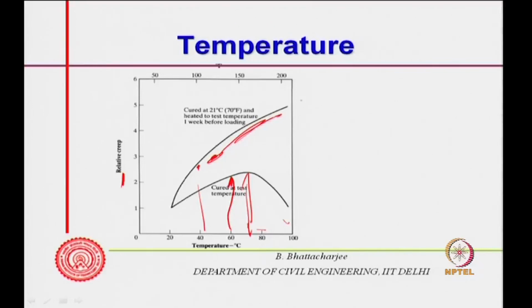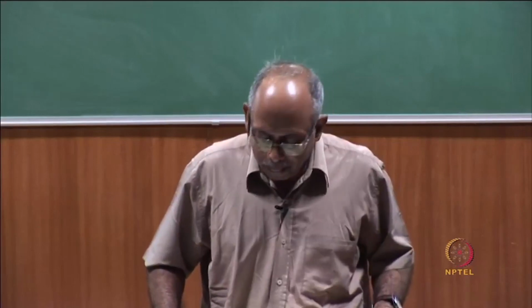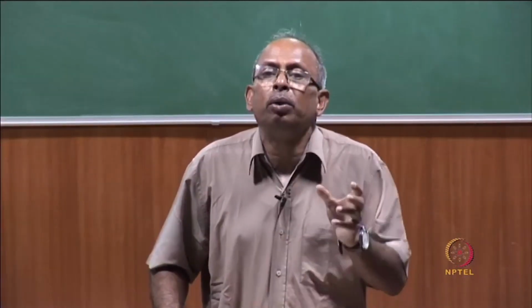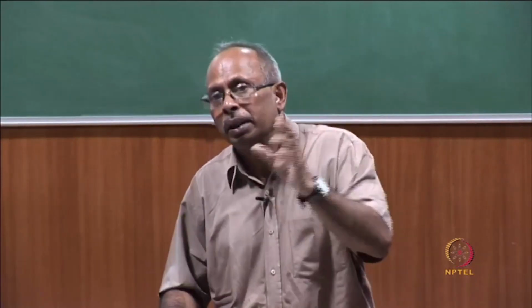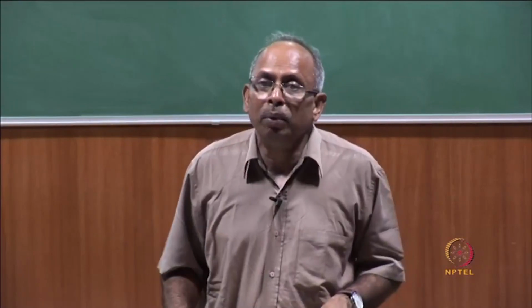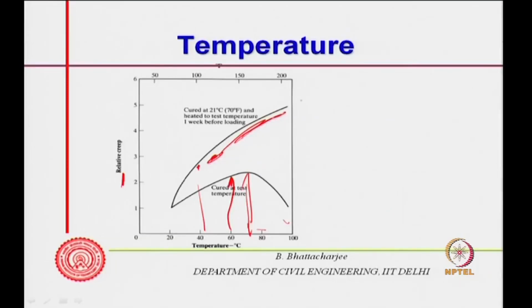So, what you are doing? You have actually cured at 21 degree centigrade, right, and heated to test temperature. Then you heat it to 40 degree centigrade or 60 degree centigrade and keep that sustained loading under that same condition. So, now what happens is there is an increase in the creep. So, you have 21 degree centigrade cured and this situation, but here cured and tested at this temperature. So, you do curing at 40 or 60 degrees centigrade.